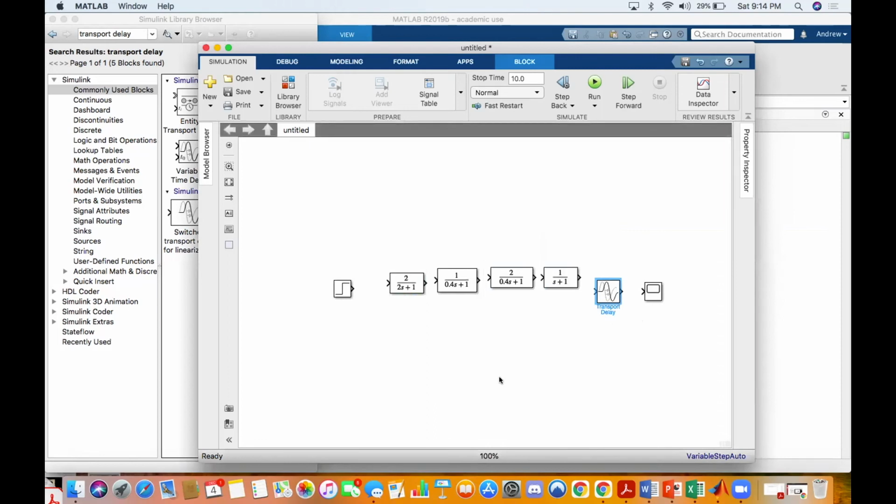So we can set the time of our model to run for however long we want in the top, as you can see here where stop time is indicated. So let's set our runtime to 50 seconds. The x-axis of our plot will eventually go to 50, and the y-axis will automatically scale to show us the entire response until a time end of 50. It is often a good idea to set the time to a relatively high value to ensure that we see the entire picture. If a response does not look as good as expected, increasing the runtime can sometimes be helpful.